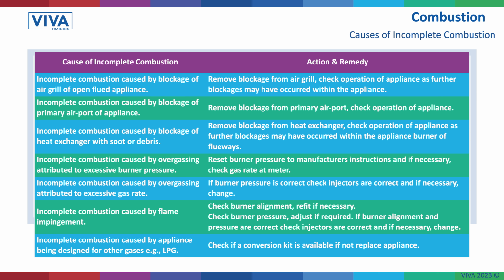A little bit like if you got a candle and put a saucer over the top of it, you'd end up with a black mark on it. That's the same thing. That's the carbon that's produced from combustion. So again, we'd remove the blockages, we'd clean it out, we'd give it a good service. Incomplete combustion caused by overgassing.